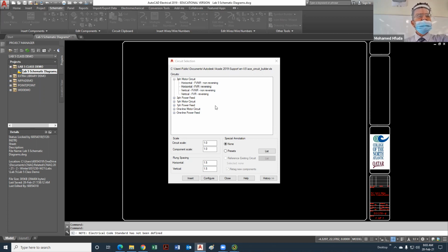Like in this building, we've got a three-phase supply, 415 volts. So divide by √3, you get 240. You're reducing it from 415 to 240 per phase. And then when the motor is running, it goes back to delta, so that each phase is getting full line-to-line voltage. Why do we do this? To reduce the inrush current, not because of protecting the equipment.